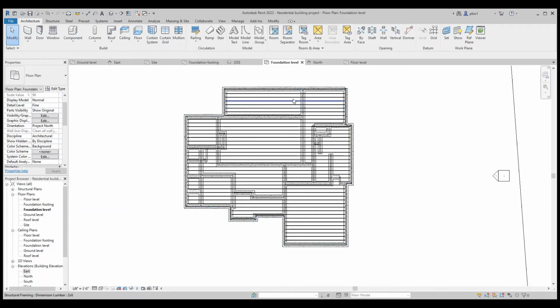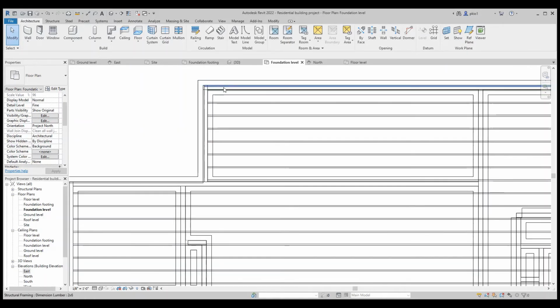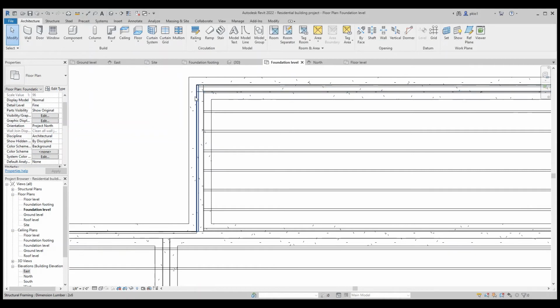In order to put the bottom plates, we will use the 6x2 columns and align them. So similar to what we did for the sill plates, we put the bottom plates on the flooring now.